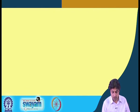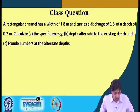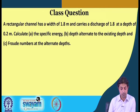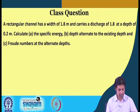All right. So another question, it says a rectangular channel has a width of 1.8 meters and carries a discharge of 1.8 at a depth of 0.2 meters. Calculate specific energy, depth alternate to the existing depth, and Froude number at alternate depths. All right. So in the beginning we don't know what type of question this is, hydraulic jump or not hydraulic jump, but this is a standard problem of open channel flow. So, we should start by writing down what are the things that we know from before.